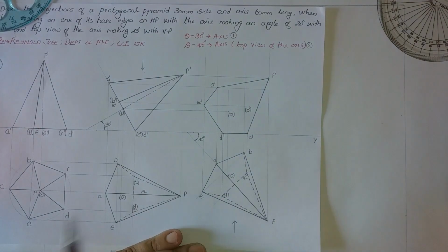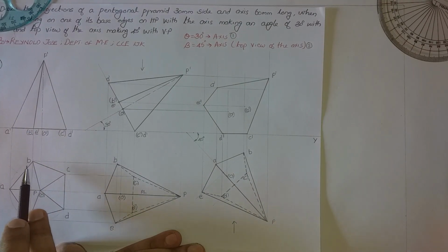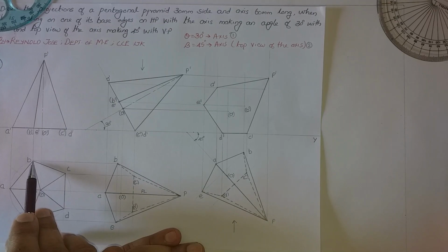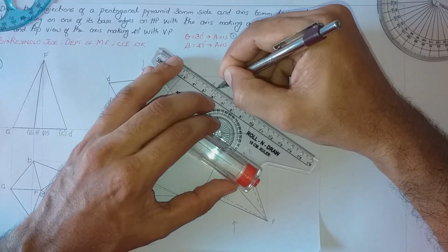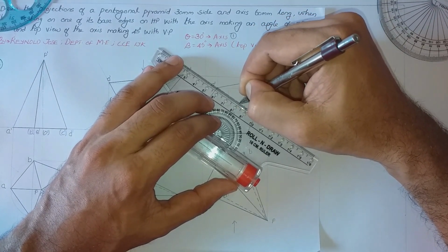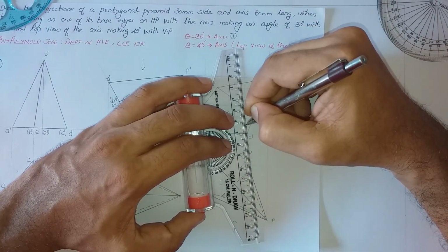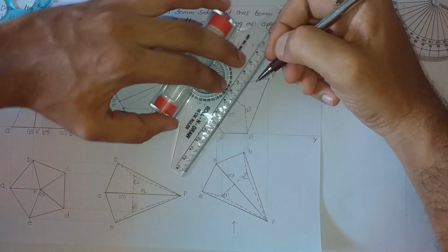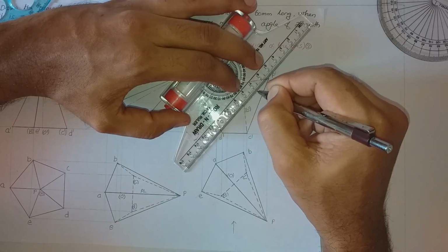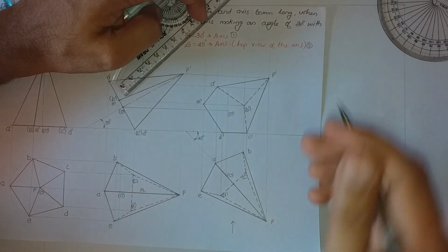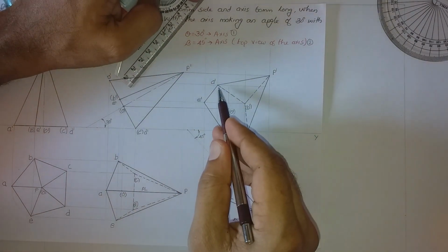So which are those invisible edges? For finding out invisible edges, we shall come to this base shape. So from B, we are having AB, BC and PB. So all these 3 edges will be invisible. So AB, then BC, then PB. So all these three edges will be invisible, dash thick lines. Now we have done with all the invisible edges and all the base edges AB, BC, CD, DE and EA.